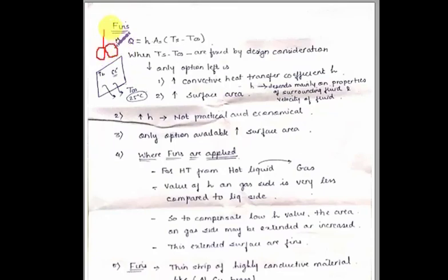So this is called forced convection. Is it possible for me every time to increase the h by installing such a fan? The answer is that it is not always preferred, because for improving the h you will require a fan or a blower, etc., which will again consume power.